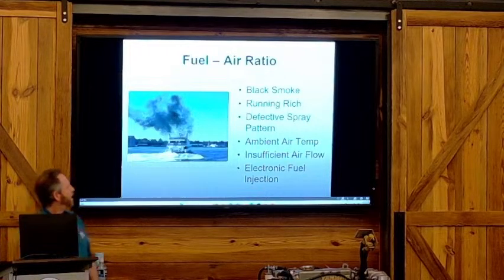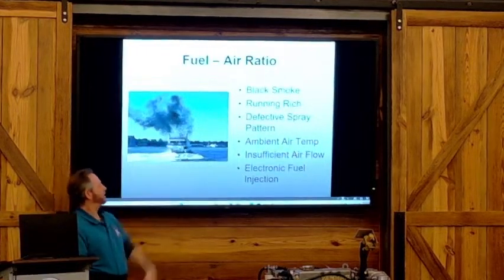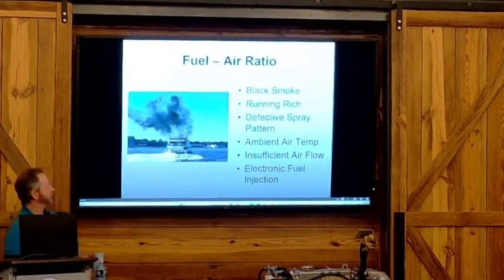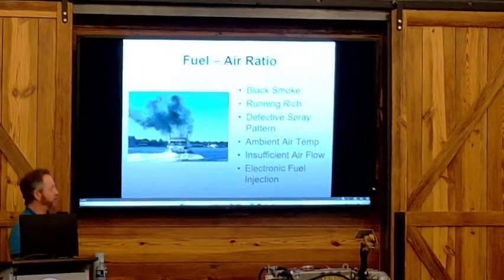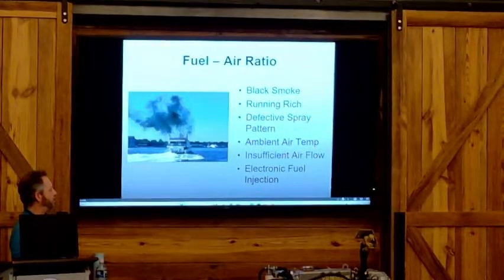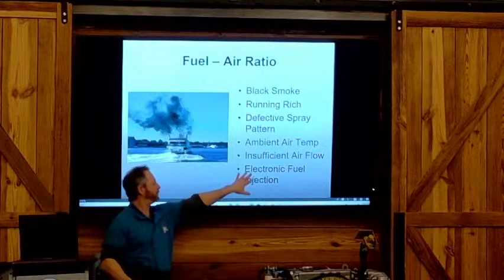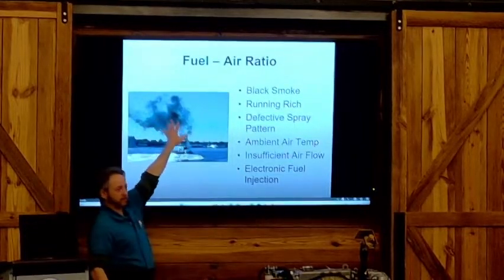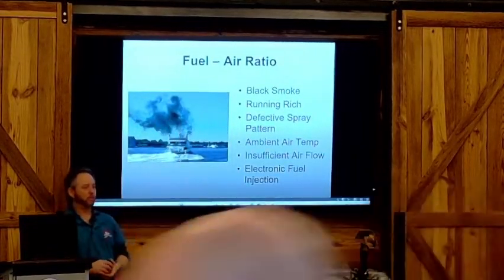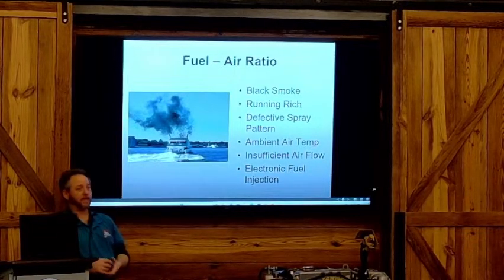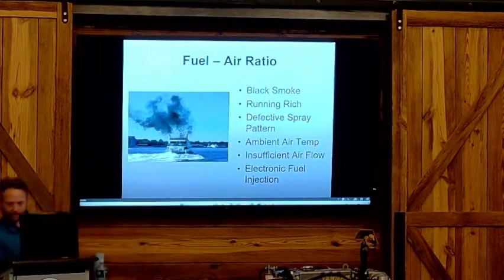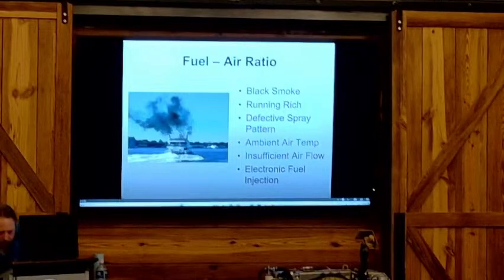All right, black smoke is because we're running rich, so we've got more fuel than the amount of oxygen. Causes include defective spray patterns, high ambient air temperatures, and insufficient airflow in or out of the engine. And like I said, electronic fuel injection will do away with this because the computer won't allow it. It will try not to allow it.